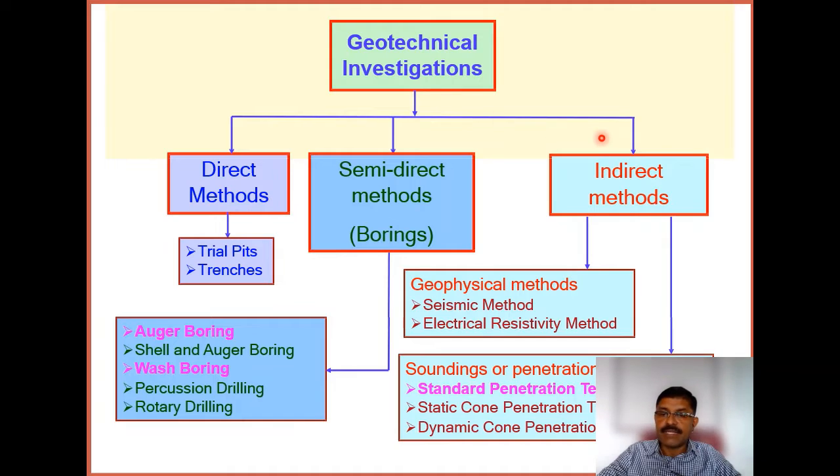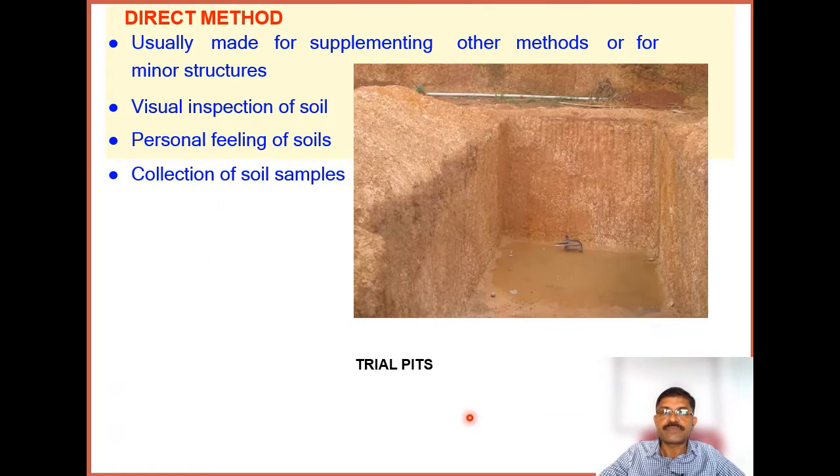Then there are indirect methods. Geophysical methods are there, seismic refraction method, electrical resistivity methods, etc. And sounding or penetration methods are there. Standard penetration test is one of them, and static cone penetration test and dynamic cone penetration test.